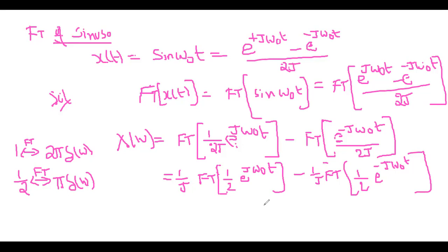The Fourier transformation equation, there we have x of omega is equal to integral minus infinity to infinity x of t e power minus j omega t dt. See, if I am substituting the 1 by 2, it is e power minus j omega t, integral minus infinity to infinity 1 by 2 as the x of t signal, my dear students.